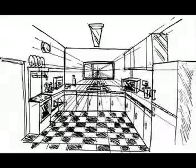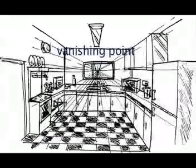If one axis is parallel with the picture plane, then all other elements are either parallel to the painting plate or perpendicular to it. All elements that are parallel to the picture plane are drawn as parallel lines. All elements that are perpendicular to the plane converge at a single point, a vanishing point on the horizon.